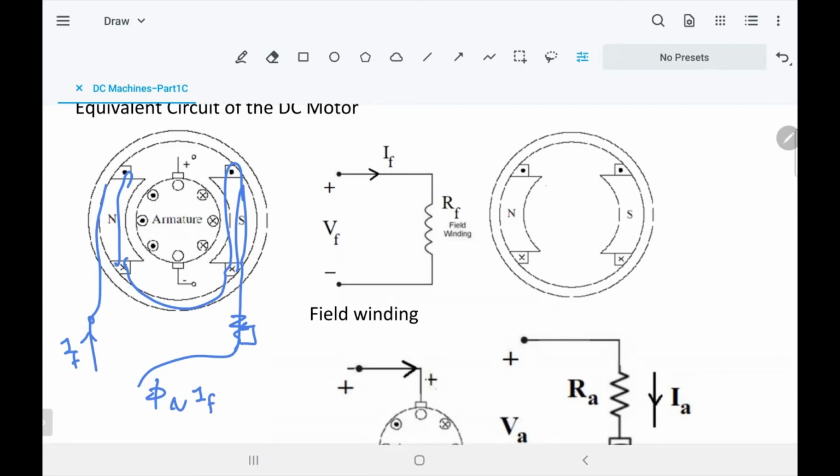And usually you put the rheostat in the beginning, when you start the experiment, on the greatest value of the rheostat, like 600 the maximum till zero. So you put it on 600. So when you start, the current will be small and the flux is building gradually. That's very important. So that's the representative of that, RF. When I'm saying RF, it means the total resistance in the field circuit.